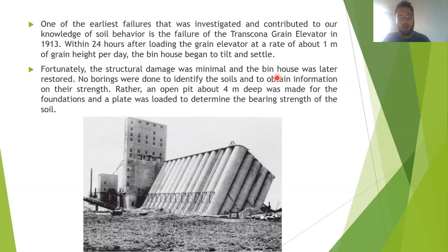Is it safe to say that soil density tests should be done prior to building? The thing is, when you're doing the soil investigation and the lab tests, soil density is one test that you need. For any kind of other test, you need soil density because it's a really huge part of the calculation. And there are two different things. One is the density of the particles of the soil, that's usually 2.65 tons per cubic meter.